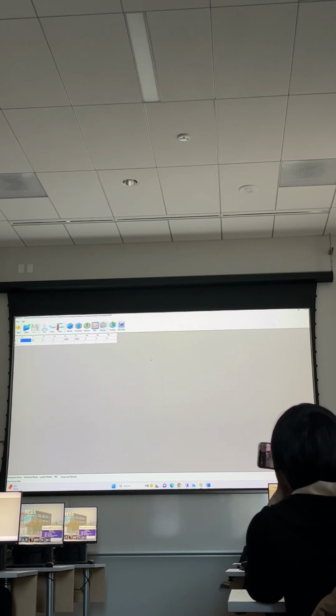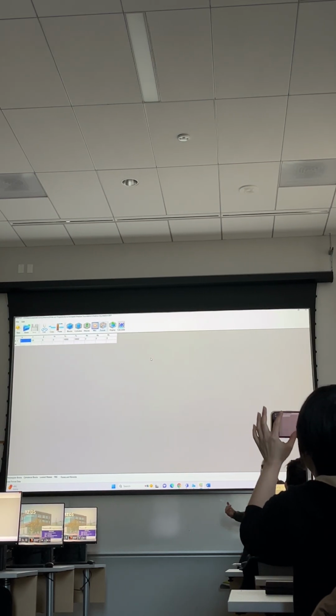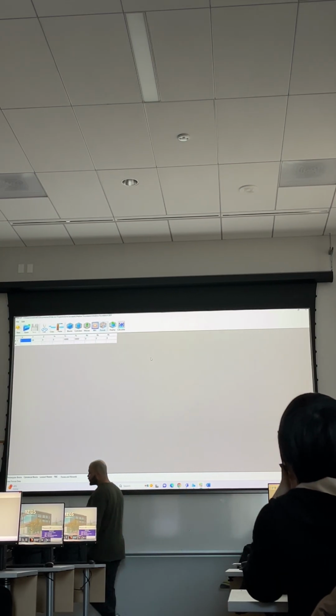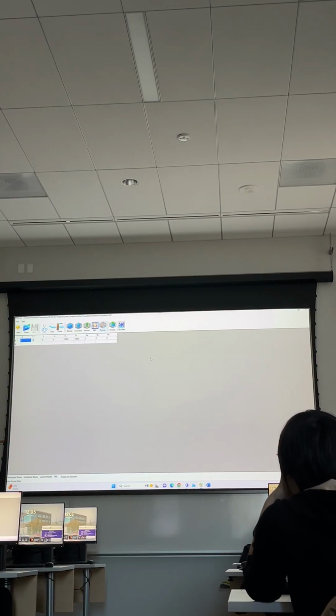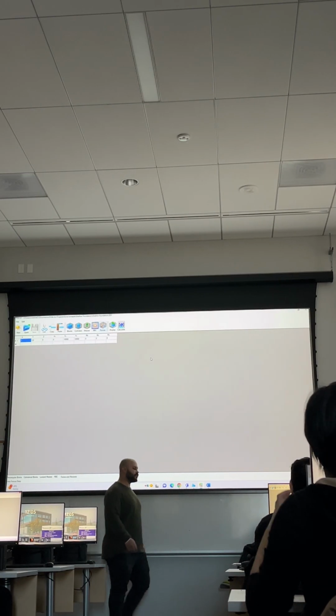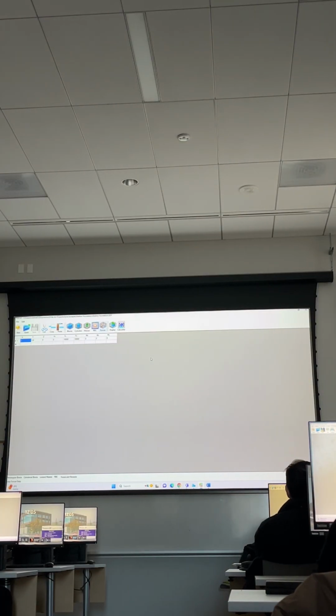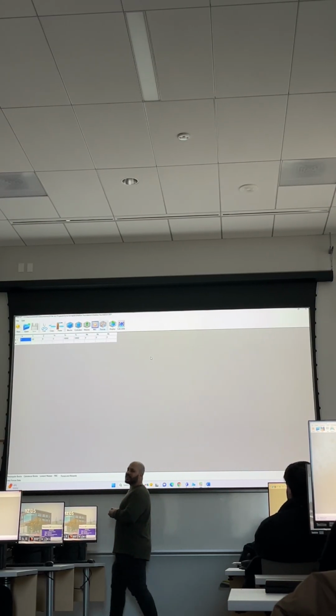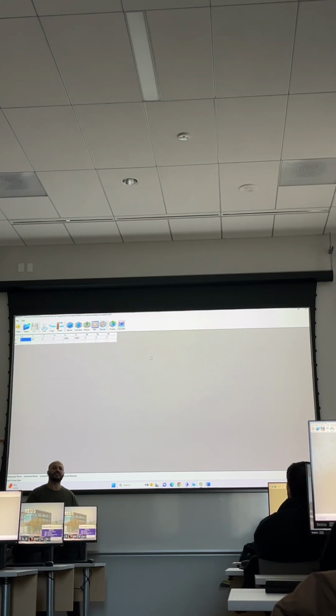Okay, you remember this step when we define the load? When we define the load here, we defined all the 10 kilonewton, which is 10,000 newton. We defined all the load in this one, right? Actually, this is not right in case we are talking about the rotating machine.